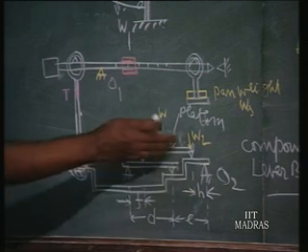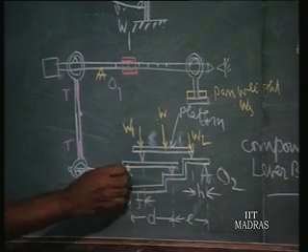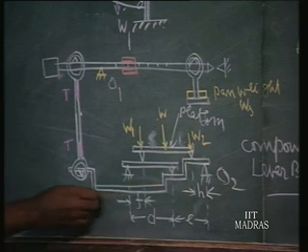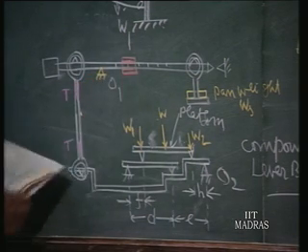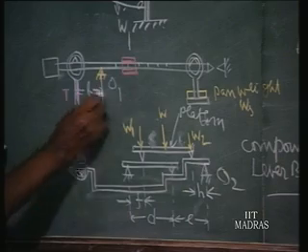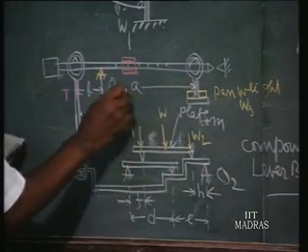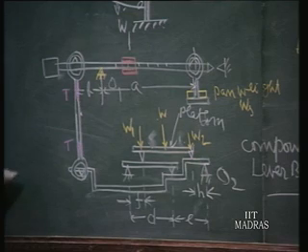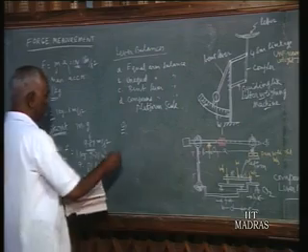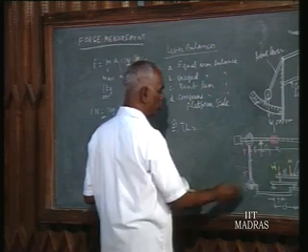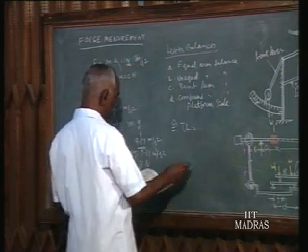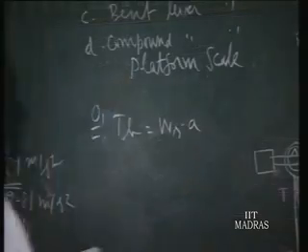For that, say here you have a platform that is mounted on another platform. One is on the lever, pivoted at O2. This main lever is pivoted at O1, and the lever edges are like this, A and B. This is lever edge B, and this is A, up to the middle. That is the knife edge there. So if you take moment at O1, you can write the equation T into B. T is the tension in the tie rod; due to the weight here you will have tension in the tie rod. So T into B is equal to Ws into A, where Ws is called the pan weight.